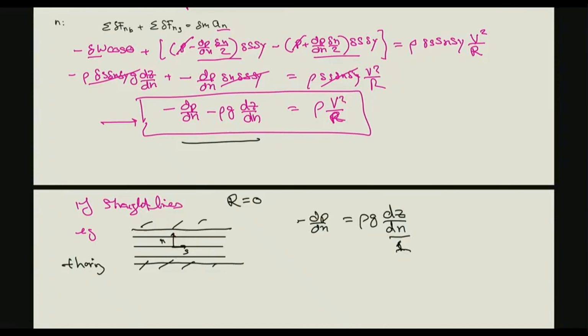And if it's, for example, gas flowing in a channel or a pipe, then unless the change in elevation is significant, we usually neglect changes in hydrostatic pressure variation. So this really has some implications on pressure measurement as well. For example, as I'll explain later, say you have flow in a pipe, and let's say it is a gas, and then you could put a U-tube manometer here and measure the pressure difference.